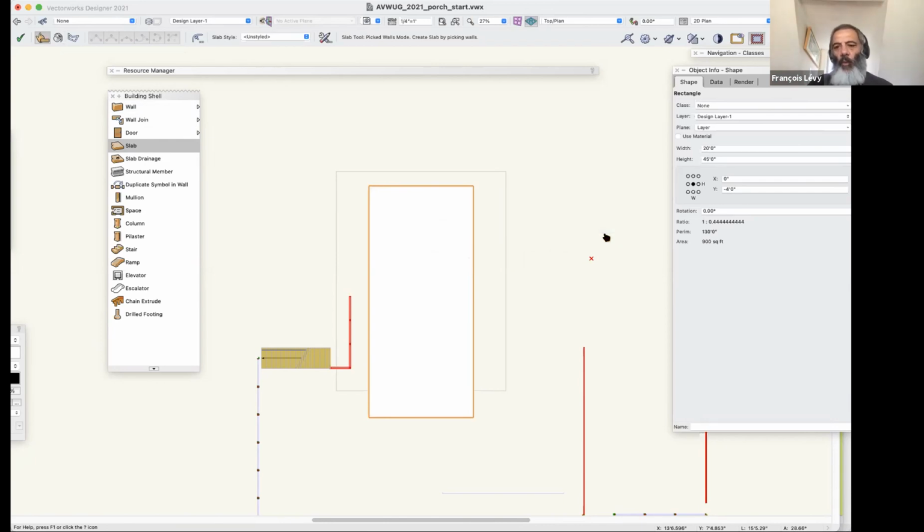I'm going to use a much more primitive tool here, which is just a floor, an older tool than slabs. There are a lot of great things to be said for slabs, but on a simple project like this, I just have the wood decking itself, and that's that. There aren't multiple components. I'm not going to model any kind of slope on it. I'm not going to subtract anything from it in 3D. So a floor is just fine.